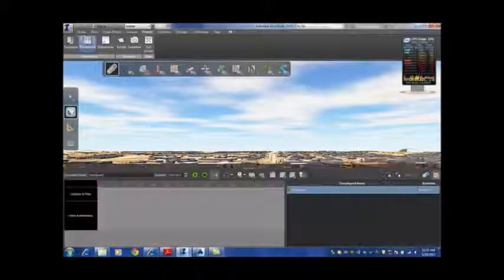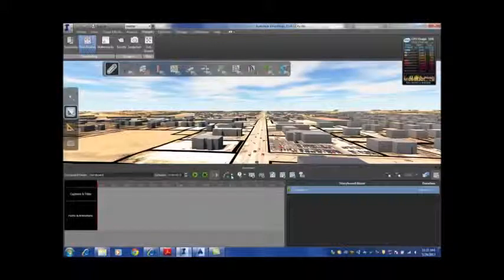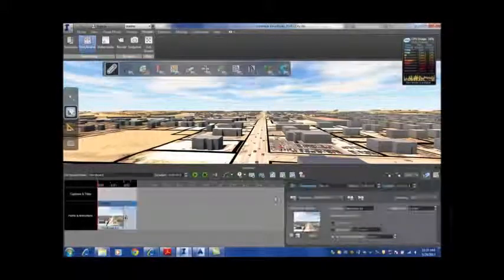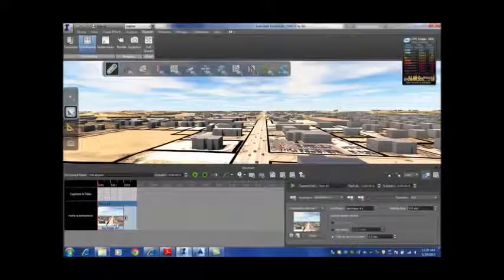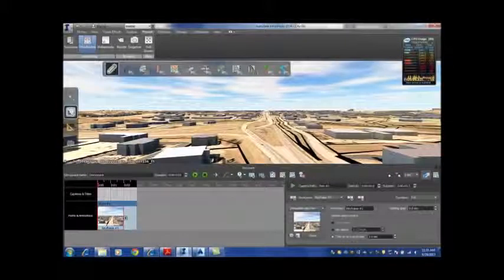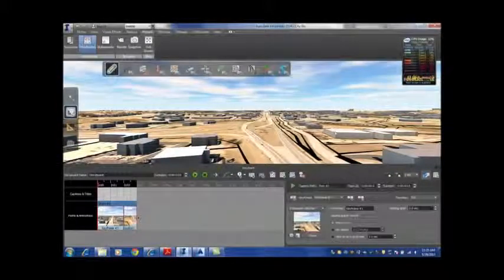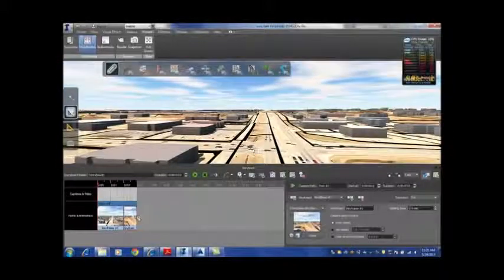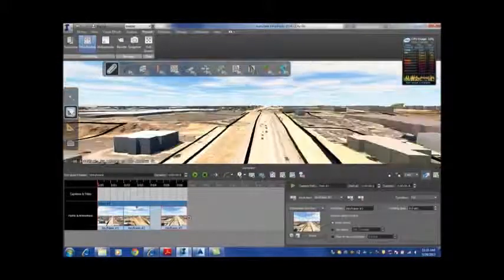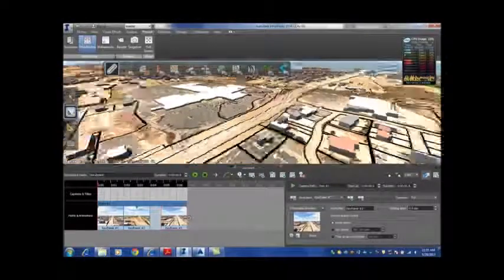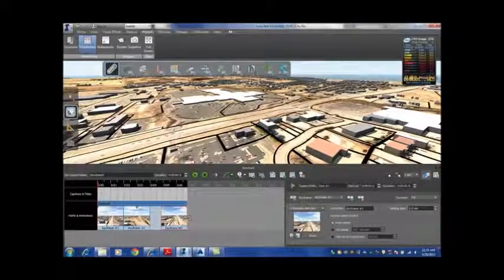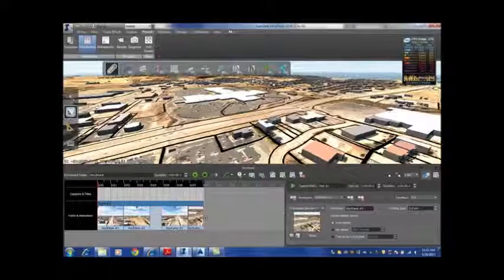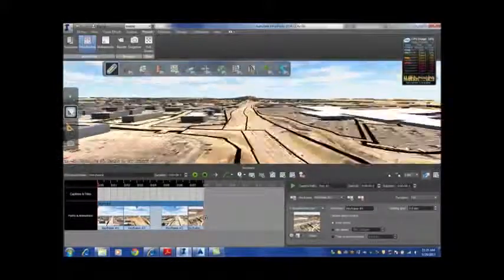I'm going to build what's called a storyboard. So if I build a storyboard and tell it that I want to add a camera path animation, it gives me my initial frame. I can just zoom forward, hit the plus, zoom forward to where I want to go, hit the plus, keep zooming, change views, change angles, okay, all the time adding the keyframes into my storyboard.